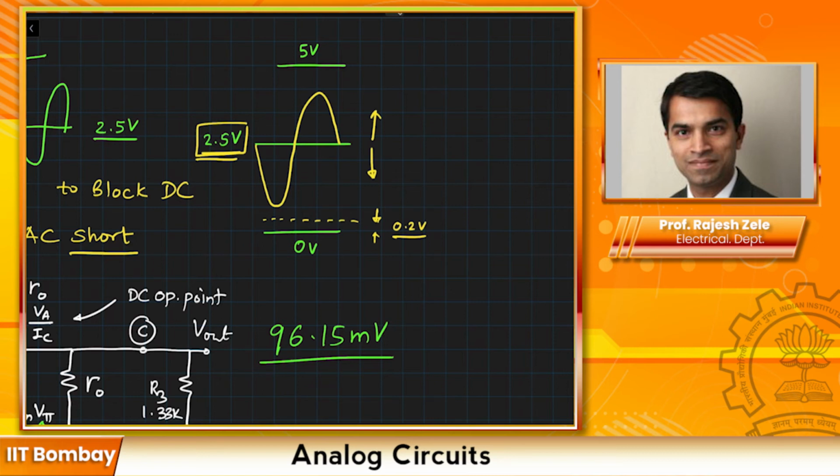So there will be full rail-to-rail swing, as we call it, at the output of the amplifier, with the caveat of 0.2 volts clearance from 0 volts. And that is because the transistor Q1 here will go into saturation. We also know that the gain is given by gm times R3, which is the biasing resistor. So I can increase the gain by increasing R3. If I increase R3, then the DC value here, which was given by IC times R3, will keep increasing.